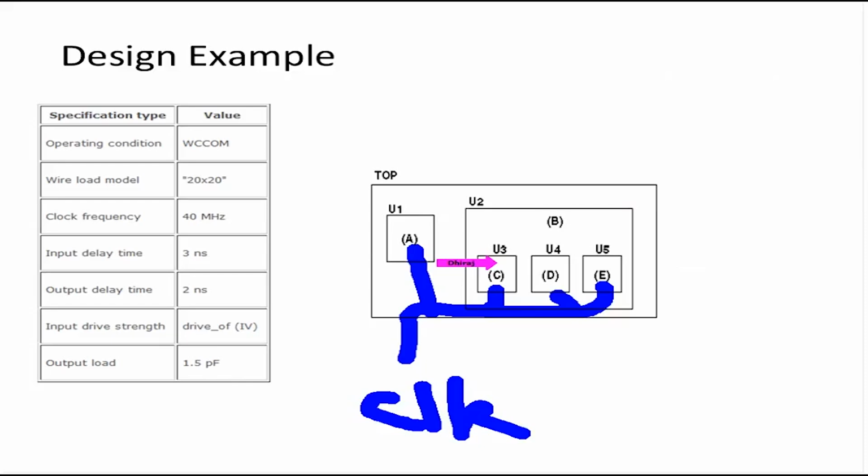Now in the second iteration, we have to use this constraint file and resynthesize. Why? Because the first constraint file that we formed was just an estimate. The second iteration has much more accurate values, and it will mostly result in a better synthesized netlist.